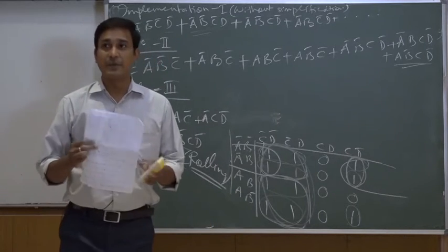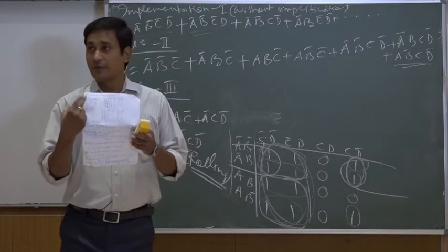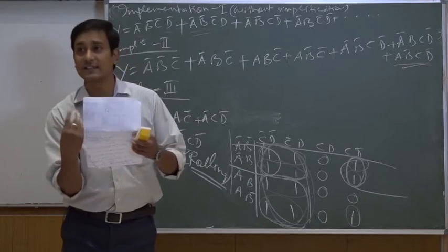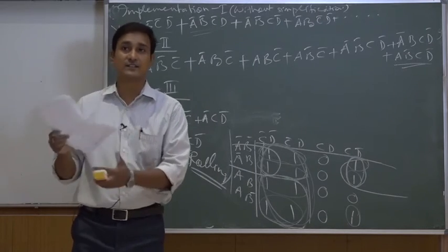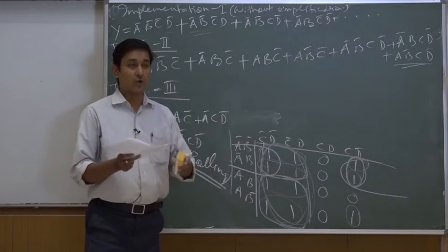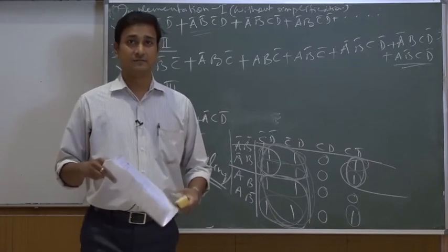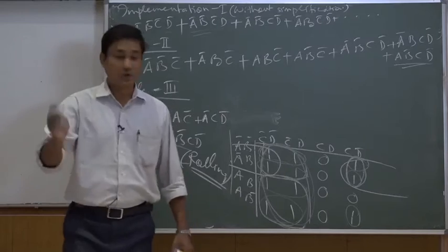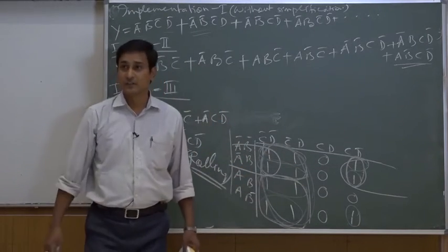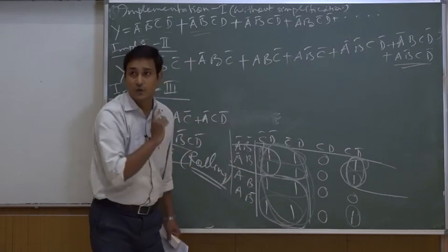It means on this paper you have put this Karnaugh map. In this paper, a few elements are on this edge, a few on this edge. Now how do they relate to one another? They are again complementary to one another so that it maintains the sequence the way you have put it. So it is just like rolling this paper like this, which will look like a cylinder or a pipe. So this has again come side by side to this column. So you are making them a group.